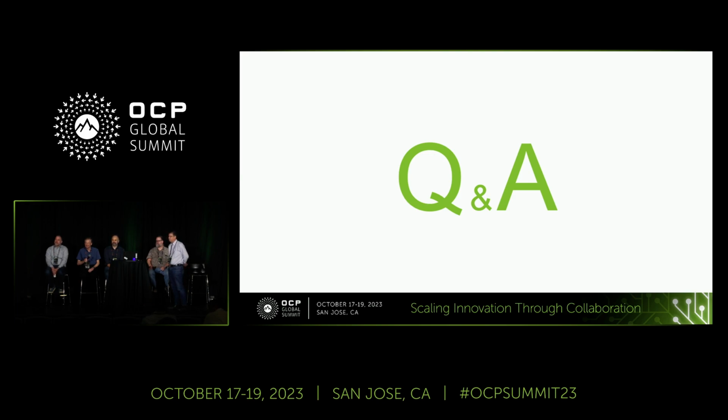Second question: SATA calls it device internal state data. NVMe calls it telemetry. Everything that was said about health checks and all that, is the OCP SATA spec going to converge on some of these same ideas, human readable telemetry, debug data, all that? What's your answer? So absolutely yes. We are planning on doing a rev of the SATA SAS spec here coming up, now that we've got 2.5 out of the way. And that is definitely one of the items that's on the docket, at least for me.